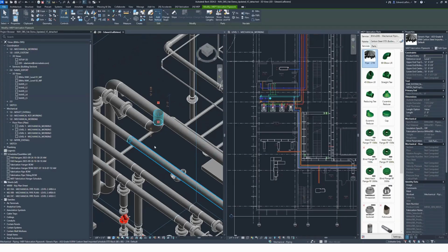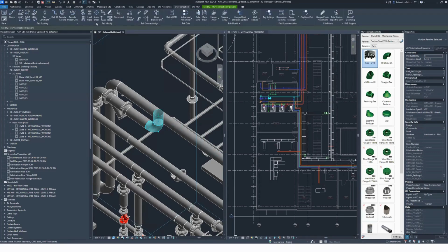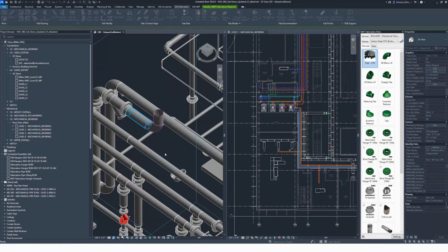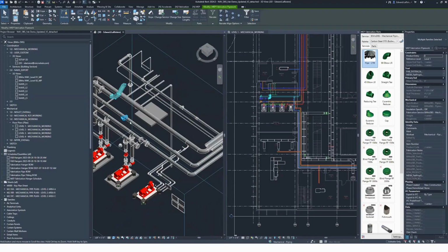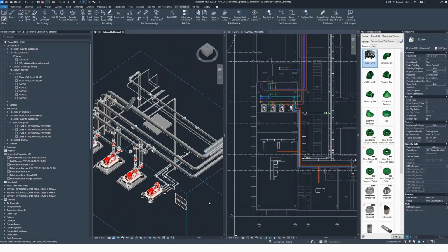We'll notice it maintained my selection, which makes it really easy to grab that whole end chunk of elements, because I'm going to leverage another Naviate tool called Rotate Fitting, where Rotate Fitting is going to let me take that whole chunk of elements and rotate about that straight. I can drop that thing down 45 degrees. So we're going the right direction, and now we're down to that last step really. Just need to get those things aligned and trimmed back together.